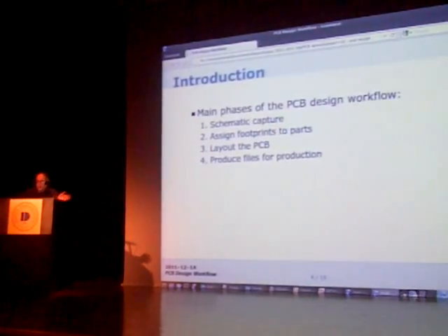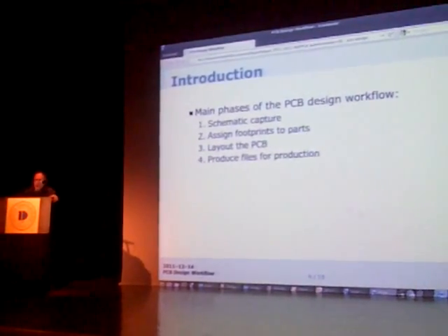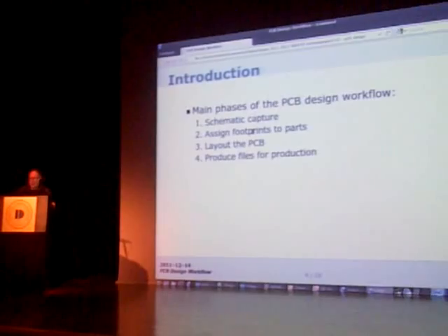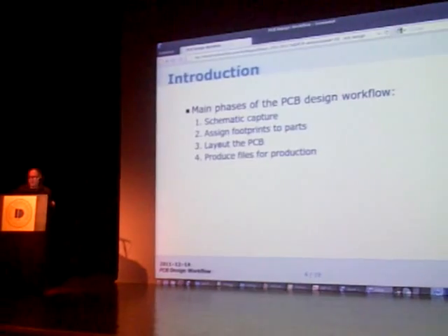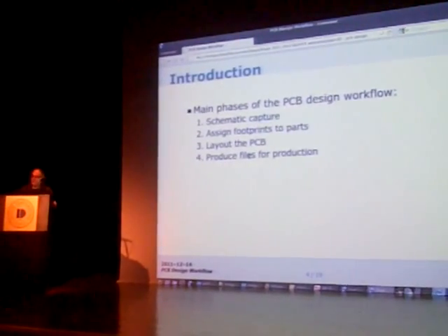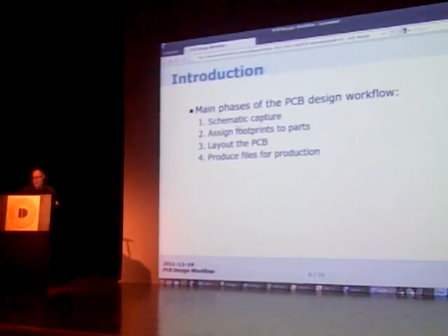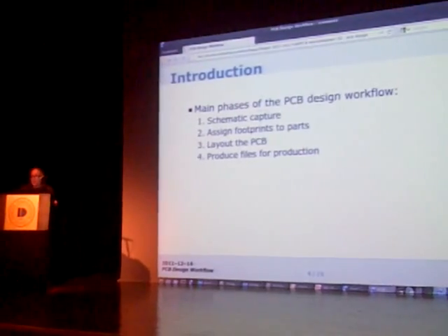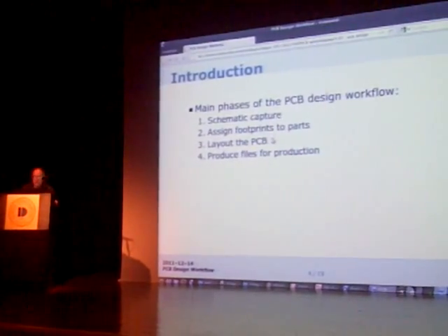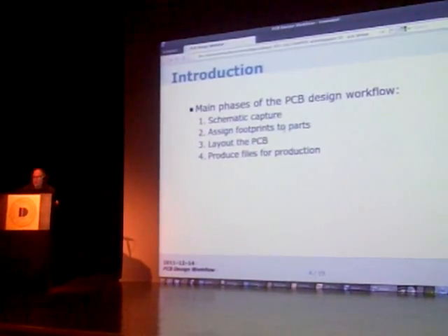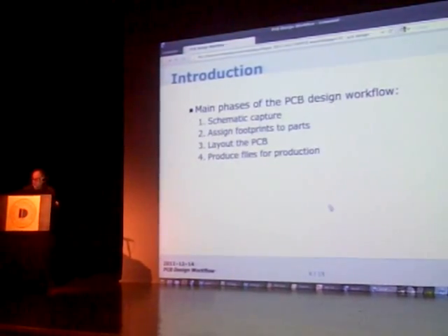Before that, though, I want to give you some idea of what the workflow is. It begins with schematic capture. You draw the schematic, then you associate the footprints you want to the parts you use in your schematic. Then you locate your parts, place them on the actual PC board, and then you produce files for production. These tend to be very distinct phases. Oftentimes, well, almost always, the schematic capture is a separate program from what does the layout. Sometimes the thing that maps footprints to parts is a separate program. Sometimes the thing that produces files for production is a separate program.